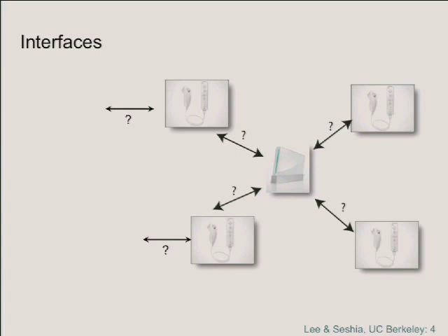You can hack it easily. You can use a Wiimote to talk to just about anything that has Bluetooth, and it can be great fun to do it. Most of our laptops have Bluetooth, so you can use a Wiimote to talk to your laptop. You can put Bluetooth on anything that has a UART by using UART to Bluetooth adapters, and then writing the code for that thing is pretty easy.